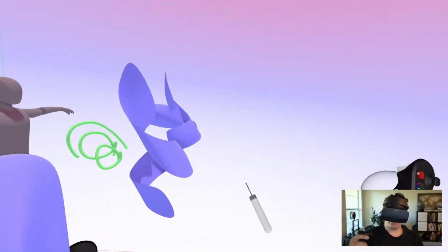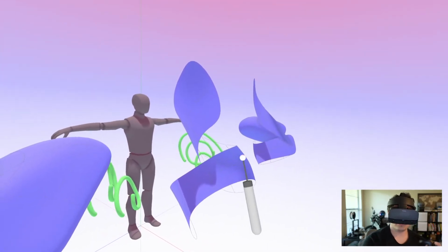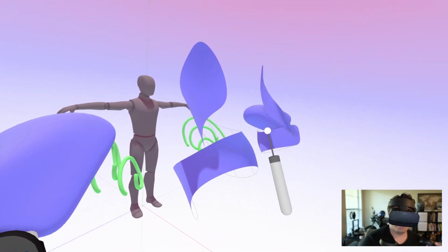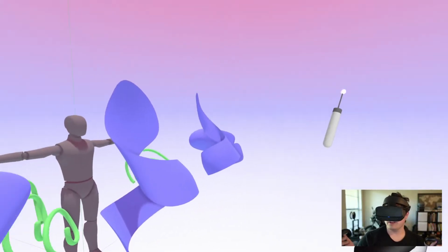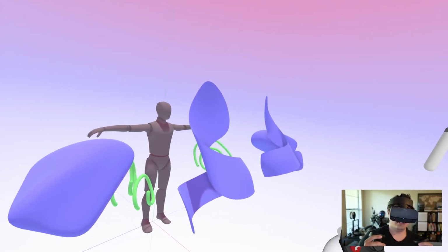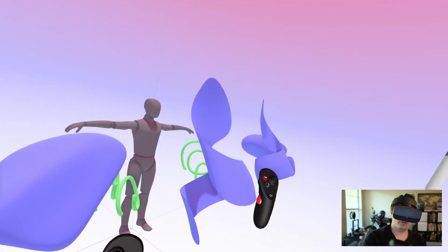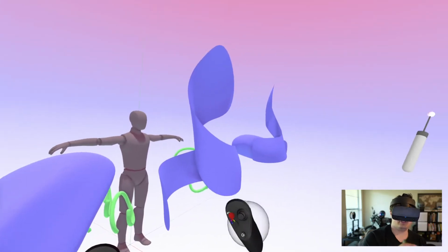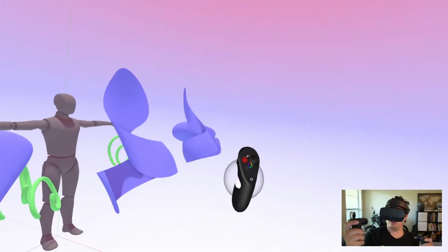This is also easily seen here when we grab it and we look at the ribbon tool. You can see how the normals on one side are solid and on the other side they're transparent, so that you can see basically how they are. And this is a standard across all 3D. This is how the software knows what side is inside and what side is outside, especially with something that has no thickness. Even though we're displaying this, technically, mathematically it has no thickness. So this is a really easy tool to reverse the normals.